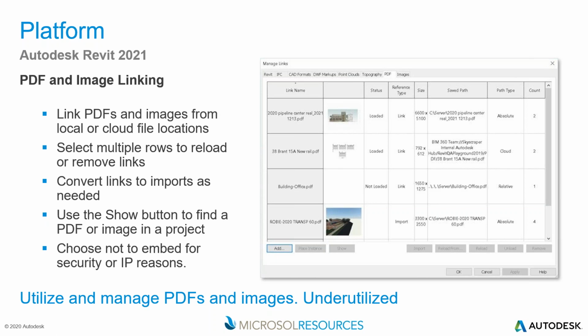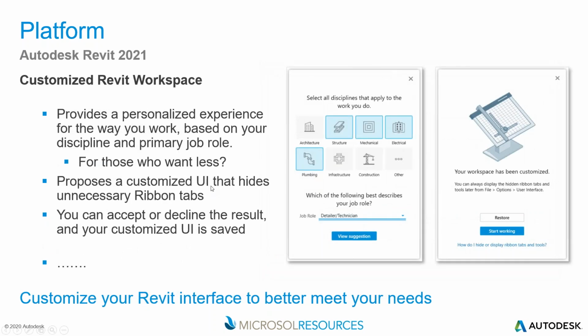So speaking of data, speaking of where it's located, you can bring images and PDFs into Revit, but now they can also be located in cloud locations. That's pretty cool because if I embed a PDF, the Revit file gets bigger. Now we can link it to another location, and being in the cloud is even better because of unlimited data size and infinite computing power. So taking images and PDFs and bringing them in is easier and a lot more manageable. I think it's an underutilized command. I'll try to focus on some of those.